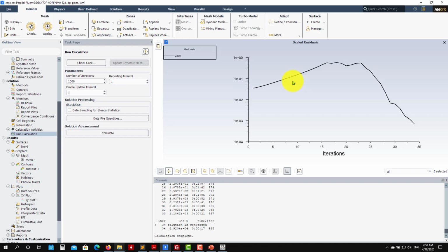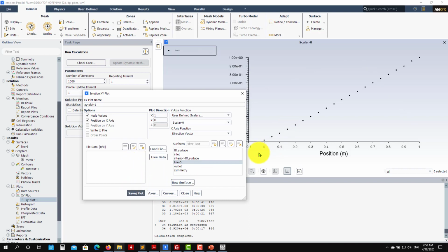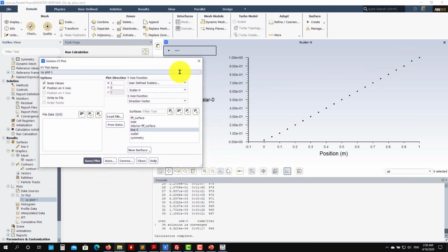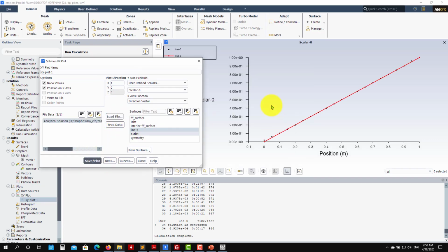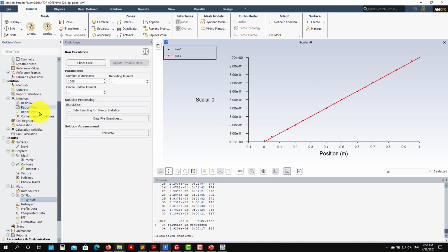Okay, remember that those k, omega, epsilon. The turbulence models can be very sensitive to these quantities. So usually Fluent does a good job estimating those initial quantities, but you can also do it manually if you want something better or you feel that what you can compute is better. So see that good agreement.